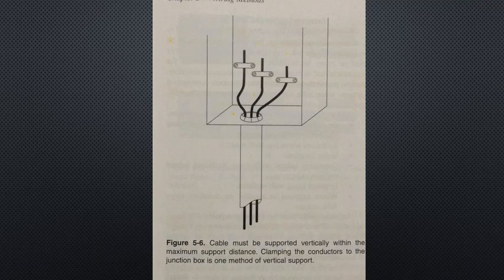Wiring within air handling spaces. No wiring is permitted within air handling ducts used for the purpose of transporting dust, flammable vapors, or cooking equipment ventilation, and plenums used for environmental air only. Wiring methods employing type MI or MC cable are permitted.